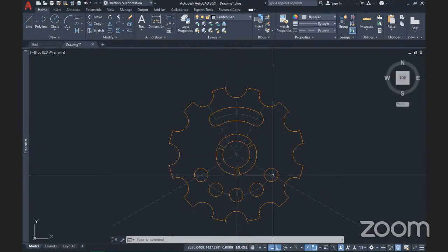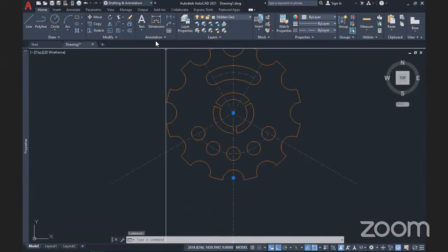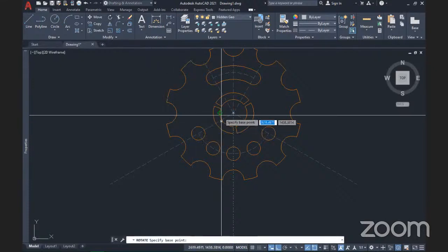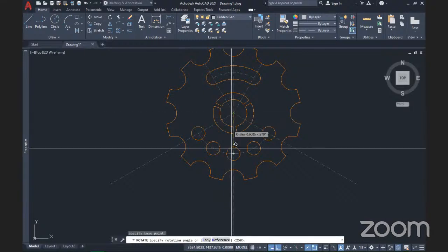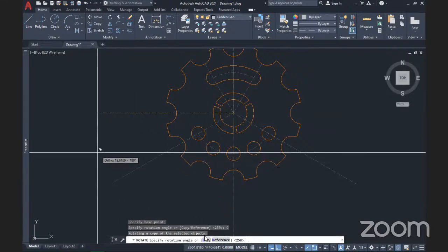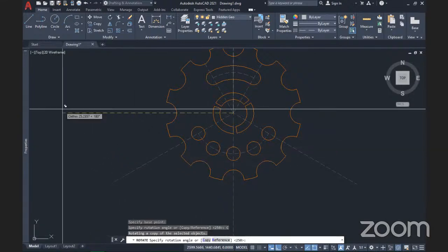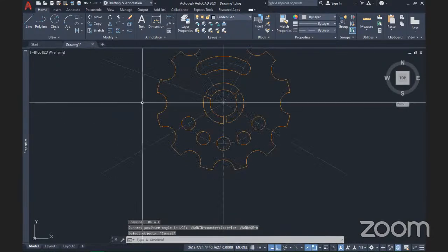Of course, remember, I can rotate and copy this item. Just click on it, click on rotate, select my base point, which is the end point of that line, or this point here. And then I'll use the copy option. After I use the copy option, I input my rotational angle, which is minus 110. Okay, I have that. So now let me start dimensioning these things.